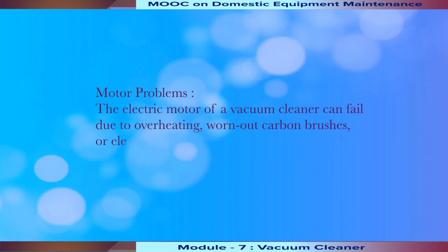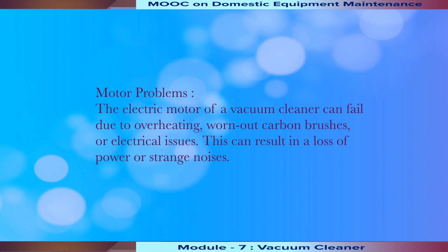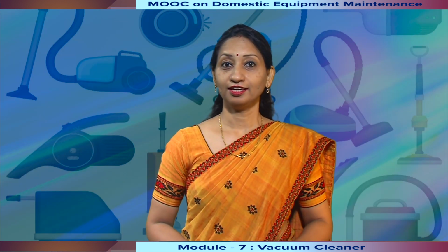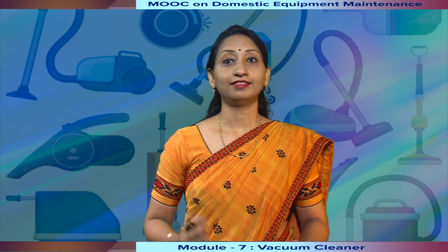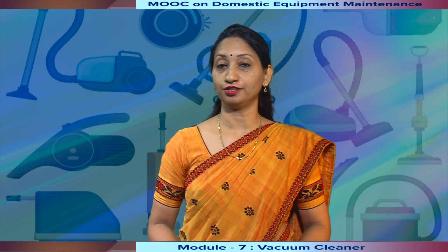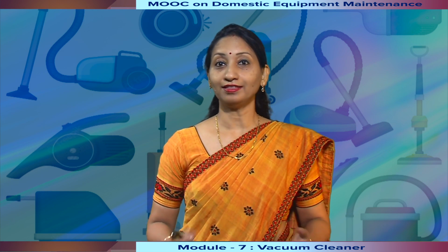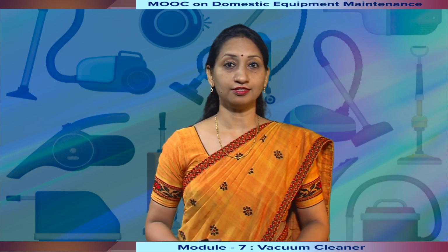The next issue is motor problems. The electric motor of a vacuum cleaner can fail due to overheating, worn out carbon brushes, or electrical issues. This can result in a loss of power or strange noise. Additionally, check the motor housing for any foreign objects or debris that could obstruct the motor's function. Similarly, inspect the power cord for any signs of damage.